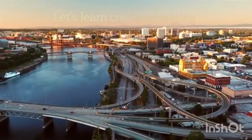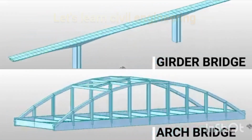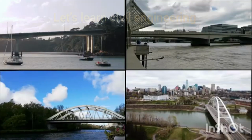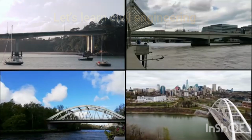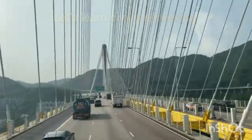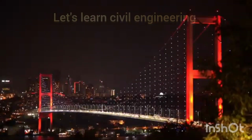We can group all bridges in the world into four basic types: girder bridge, arch bridge, cable-stayed bridge, and suspension bridge. Common wisdom suggests that girder bridges and arch bridges are good for short to medium spans, whereas cable-stayed bridges are good for medium to longer spans, and suspension bridges are good for very long spans.